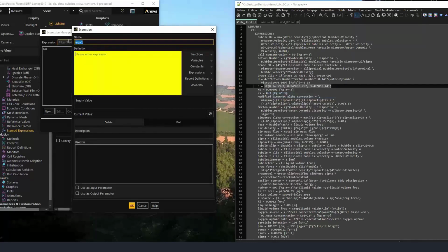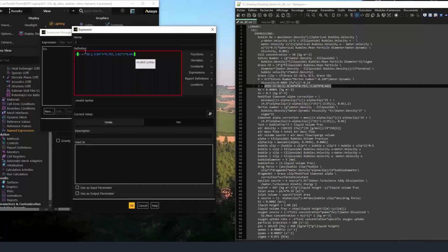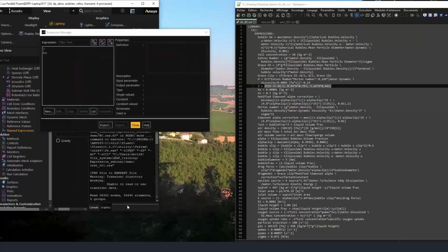I know that that's equal to my J parameter. So I'm going to stick it in here, do a Control V. I need to hit Enter to jump down. Now, this has got an invalid syntax. So very quickly, if you've been doing this, you know that the if statement is slightly different. It's just in capitals, especially if you're a Python user. So Enter. That's invalid because H is not defined, but that's okay, because we're going to want to define that later.